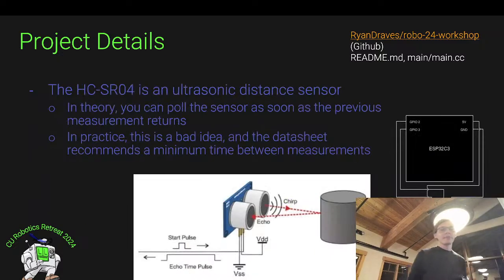The other thing you'll see on the little demo boards at each table here is an HC-SR04 ultrasonic distance sensor. So this cheap little sensor is able to measure distance, similar to bats, just by measuring how long it takes, the time of flight, for an ultrasonic sound to hit something and come back to you.